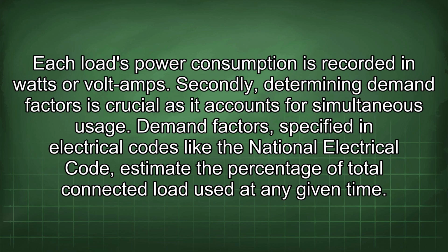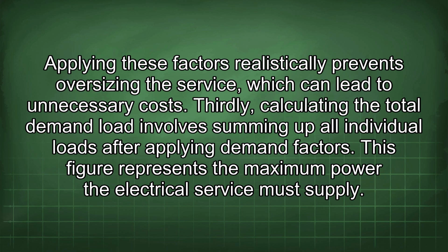Secondly, determining demand factors is crucial as it accounts for simultaneous usage. Demand factors, specified in electrical codes like the National Electrical Code, estimate the percentage of total connected load used at any given time. Applying these factors realistically prevents oversizing the service, which can lead to unnecessary costs.